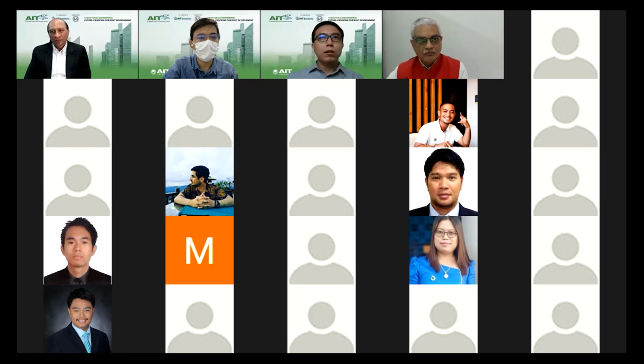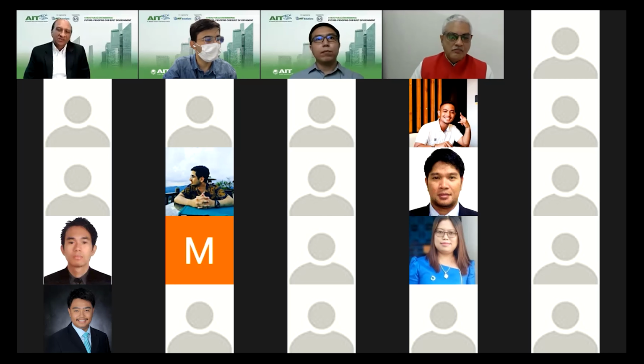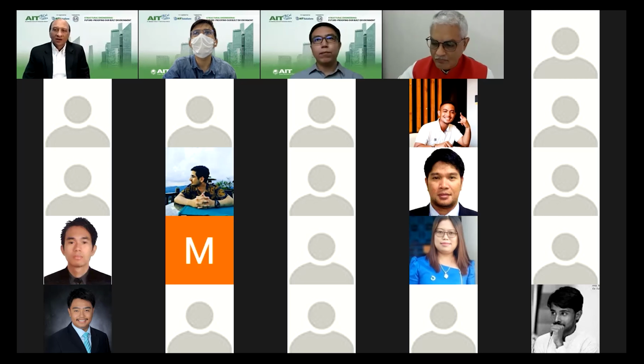Like in the morning, you remember Ron was mentioning that they use this shear wall, which is actually not covered by the code method. So they use performance-based design. They also use these BRBs there. And sometimes people now use flat slab in tall buildings, which the traditional building code will not allow. But by PBD, you can prove that they can still be used.